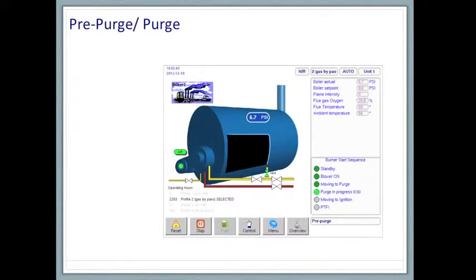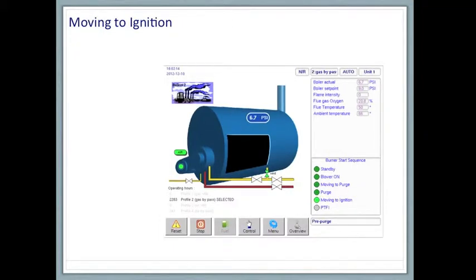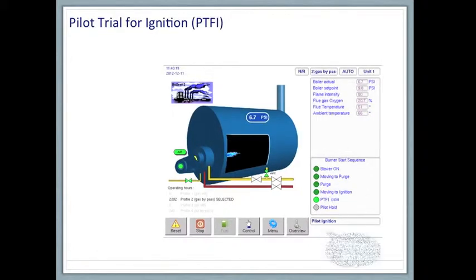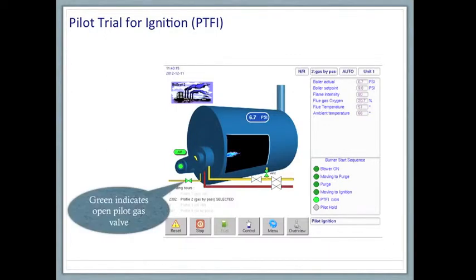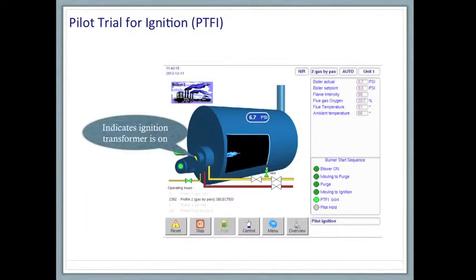Selected motors move to their ignition positions once a purge-proof signal is automatically switched off. When the drives have stopped, the control advances to ignition. The controller confirms that a pilot flame exists for 10 seconds before switching to the main ignition.